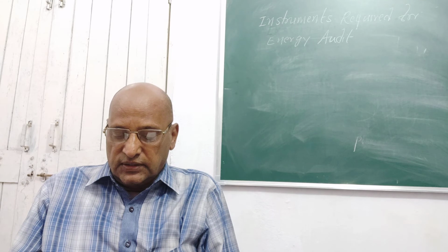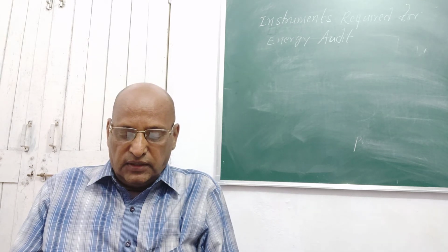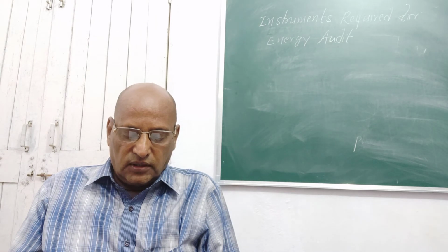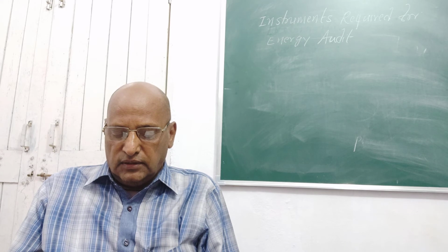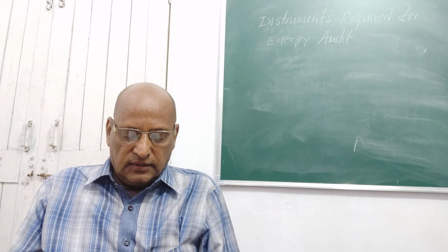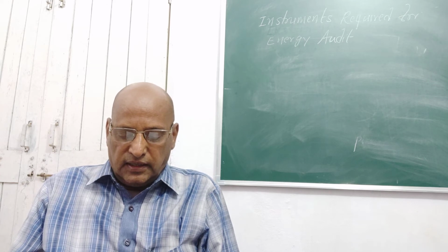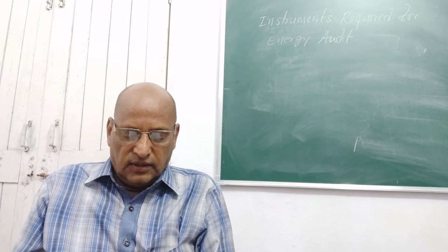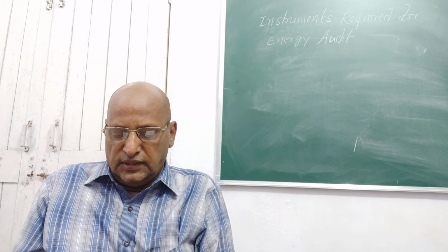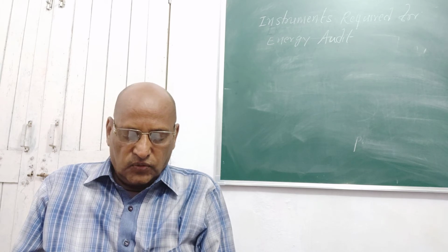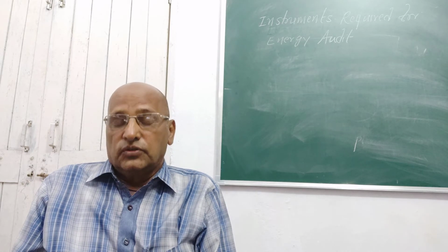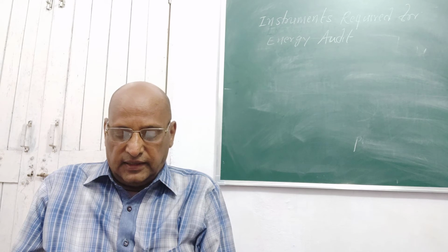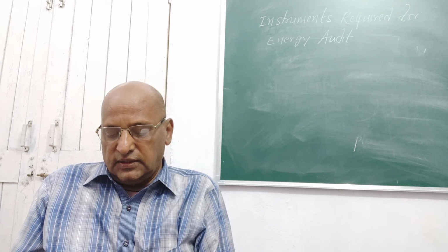The energy audit may be considered as similar to the monthly closing statement of an accounting system. One series of entries consists of the amount of energy which was consumed during the month in the form of electricity or gas, fuel, oil, coal, etc. And the second series lists how the energy was used, how much energy was used in lighting, in air conditioning, in heating, in process, etc. The energy audit process must be carried out accurately enough to identify and quantify the energy and cost savings that are likely to be released through investment in energy saving measures.